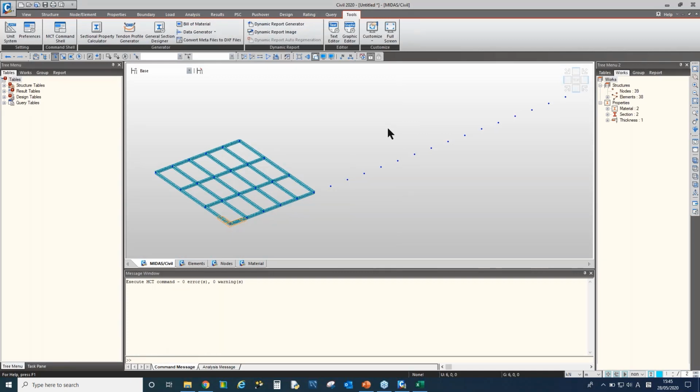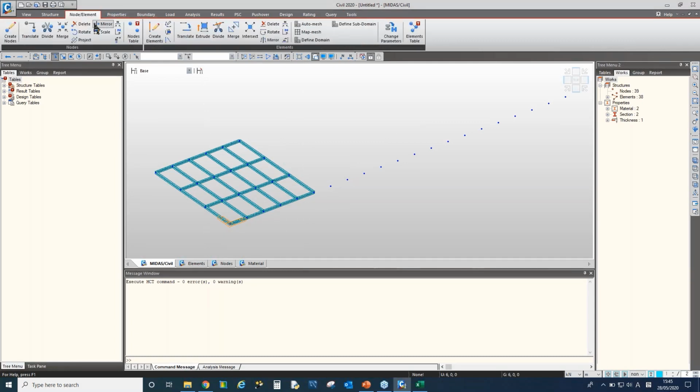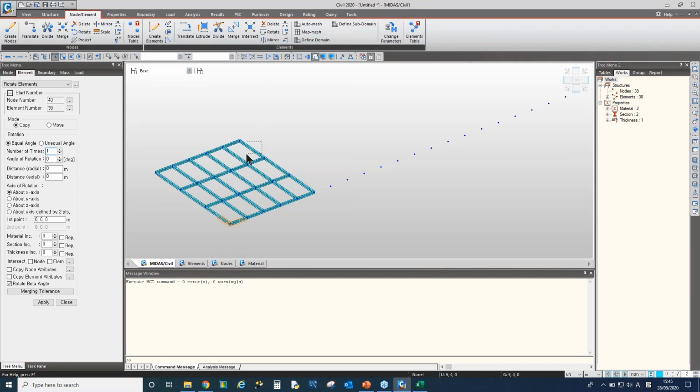So if the cross beam has radius, we can rotate, I guess, the element. So you can select the first cross beam and then input the radius of the curved bridge, and then set up the original point. Then I think you can make the cross beams for the curved composite girder bridge.